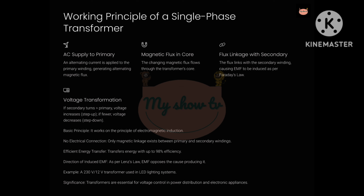This magnetic flux flows through the iron core. 3. This alternating magnetic flux links to the secondary winding through the magnetic core. 4. According to Faraday's law of electromagnetic induction, a changing magnetic field induces an e.m.f, electromotive force, in the secondary winding. 5. Importantly, there is no direct electrical connection between the two windings. The energy is transferred purely through the magnetic field.